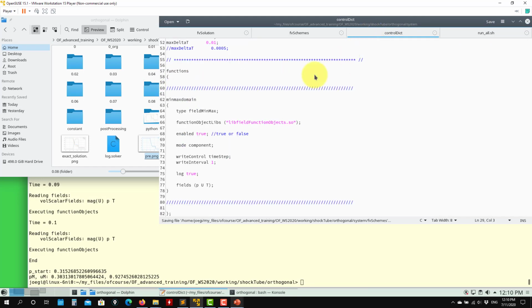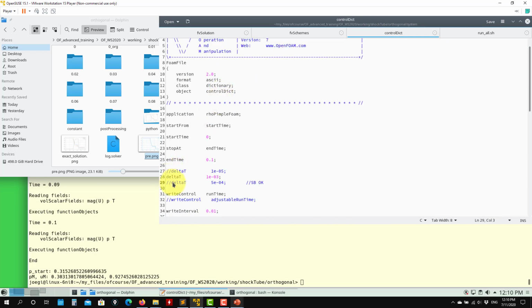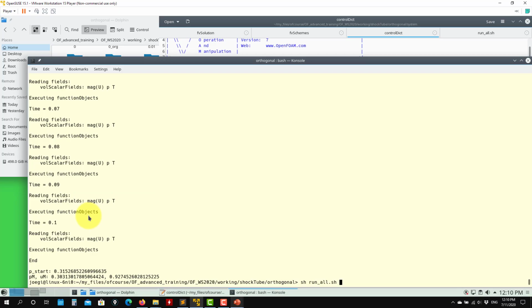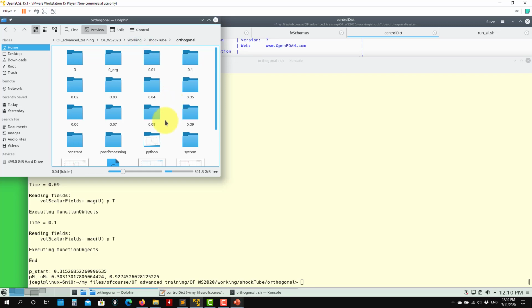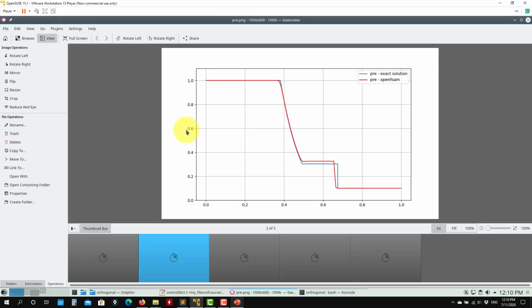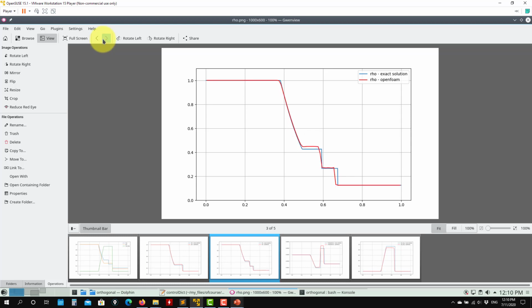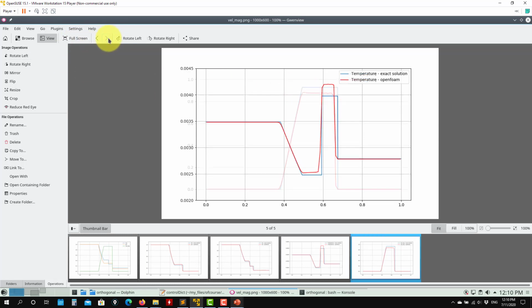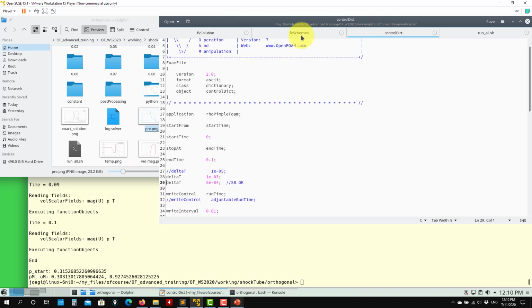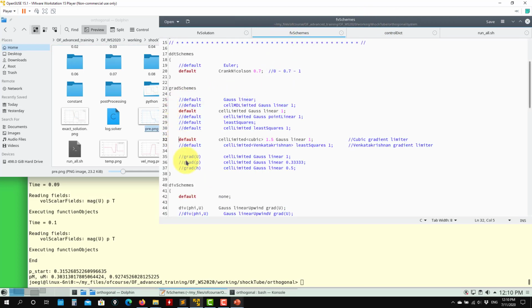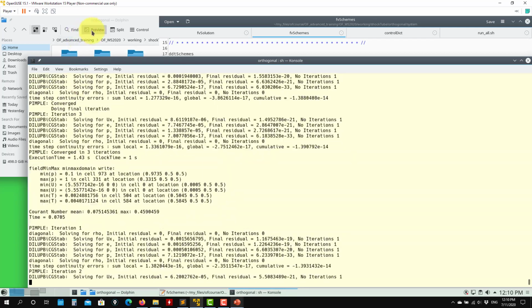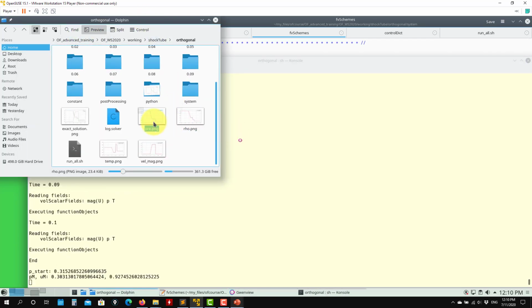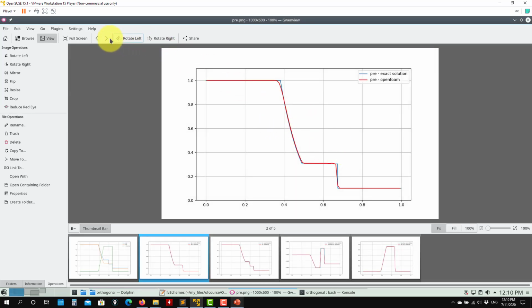So okay, also let me show you the influence of delta t just to end this one. So let me reduce it half by half. So if I run now, always reducing the delta t, the time step will improve your solution, but again it will increase your computational time. So there is some improvement there or not. Okay, so easy problem, play with all these options just to get it working. So probably here let's better go back to Euler. In this case the Crank-Nicolson maybe is not a good choice, so if we go back to Euler, see that things are getting better.